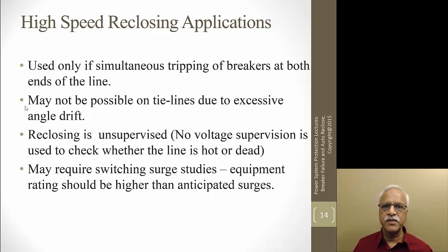In the case of transmission lines, if you are using pilot schemes, then it is extremely important to make sure that the pilot is working for both ends to reclose. If the pilot is not working, then they disable the high-speed reclosing. And it may not be possible on tie lines due to excessive angle drift.